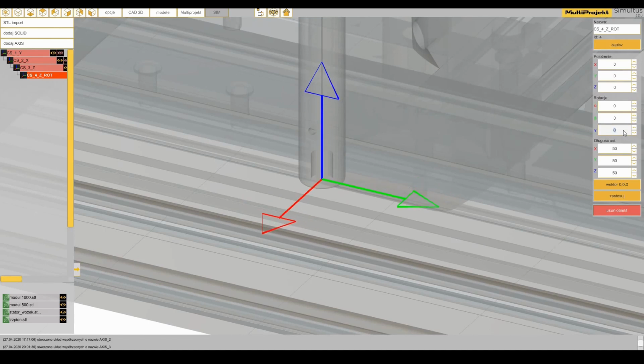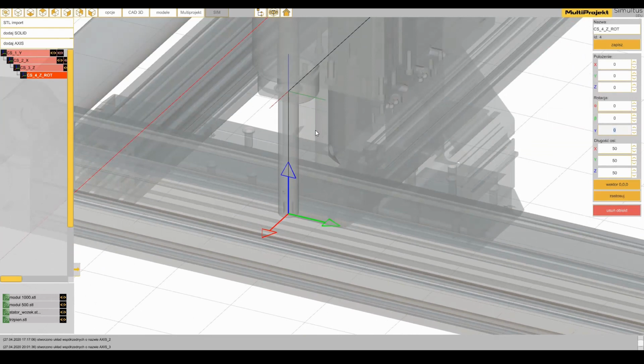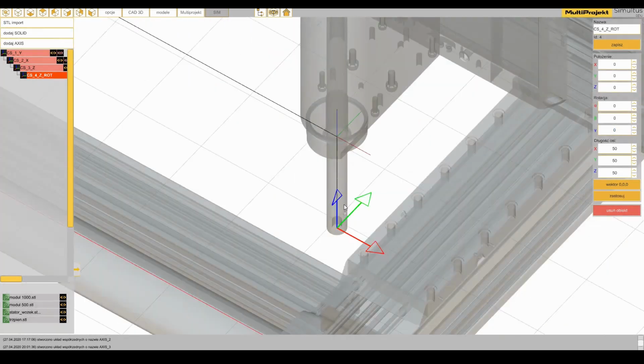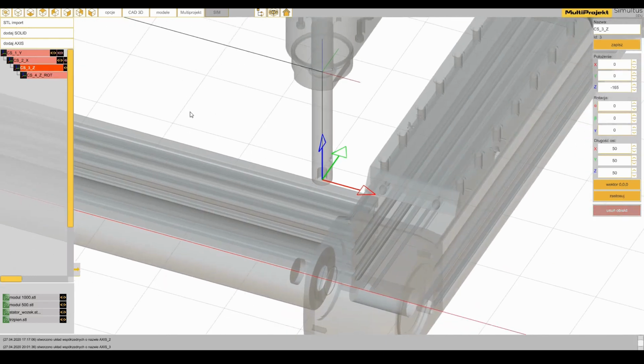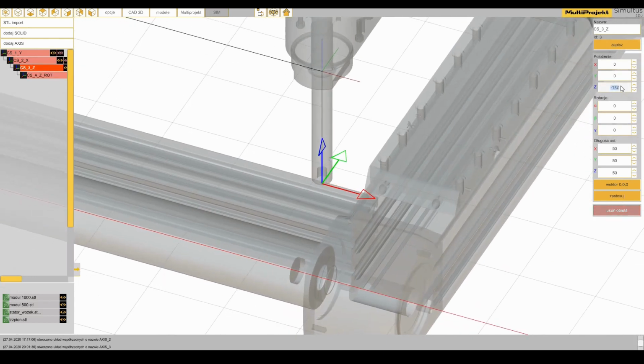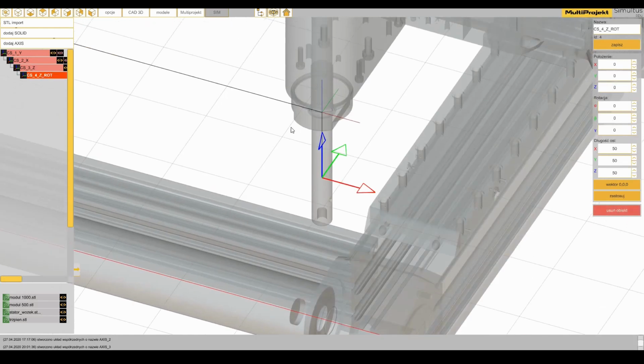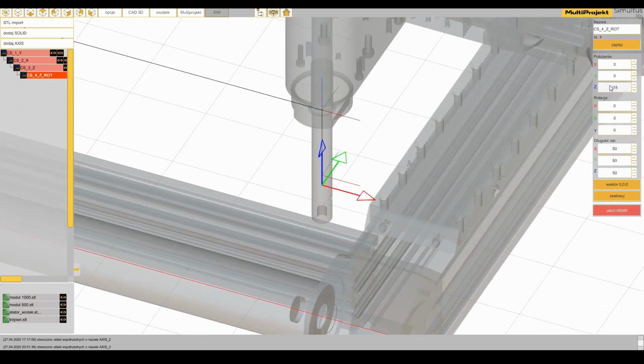As we said before, the position of the center of the coordinate systems that move in a straight line is not relevant. To make our kinematic chain more visible, let's move the third system slightly up, for example by 65 mm. And leave the fourth system at the end of the slider.